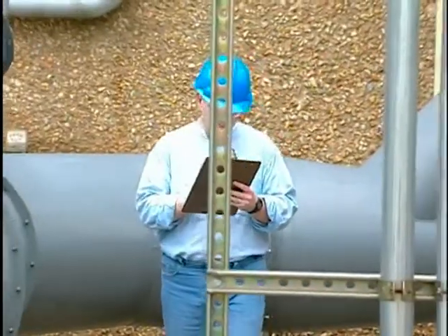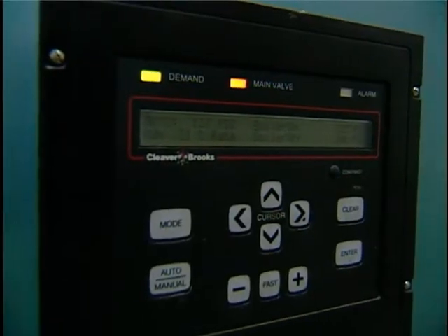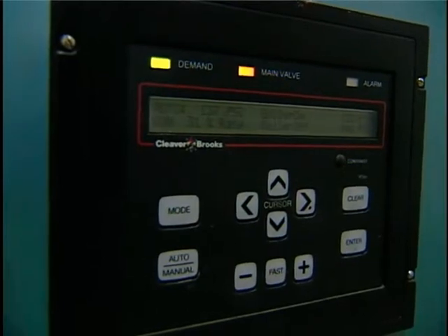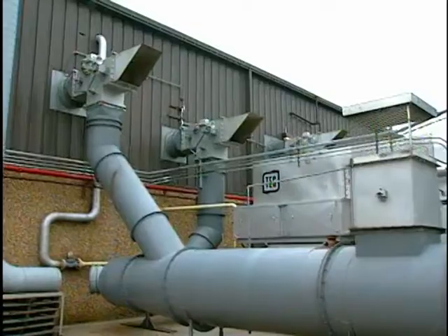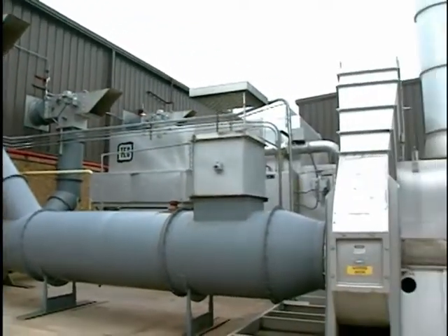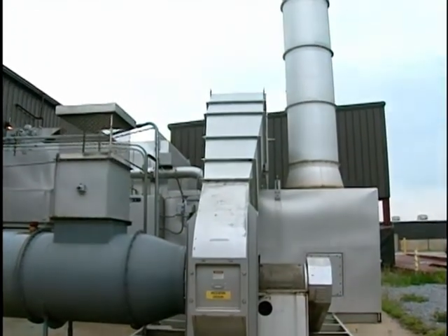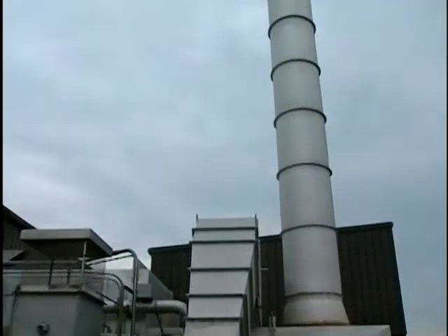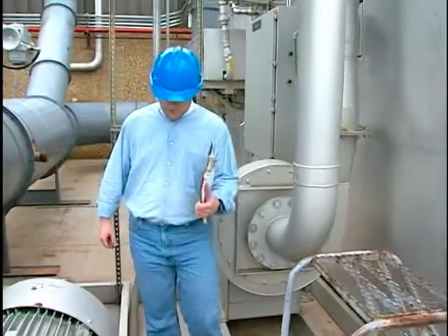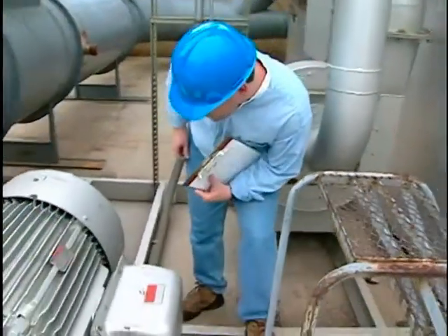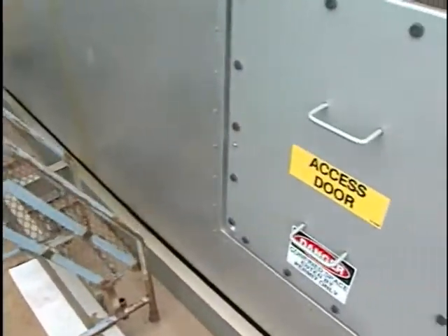These conditions are similar to those of conventional thermal oxidizers. There are some limitations in the use of a process heater or boiler as an incinerator. The boiler must operate within about 40 to 100% of the design load in order to have the necessary temperatures for organic vapor destruction. The waste gas stream should be only a small portion of the total gas flow through the unit. If the volume of additional gas is large, maximum recommended velocities through the unit would be exceeded, potentially lowering the destruction efficiency of the system. Finally, there should be nothing in the waste gas stream or its combustion products that would present a corrosion problem or cause deposits on heat transfer surfaces.